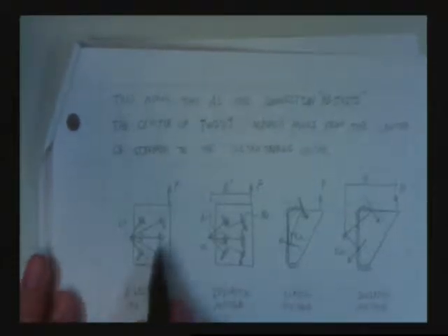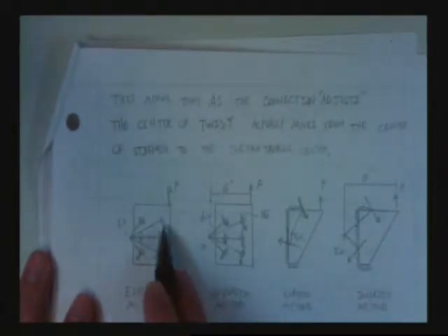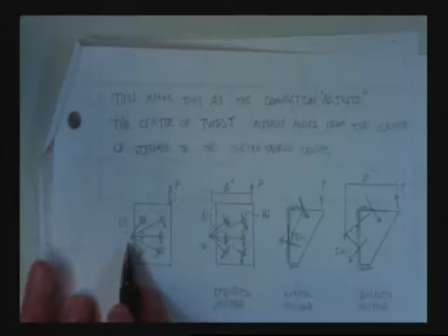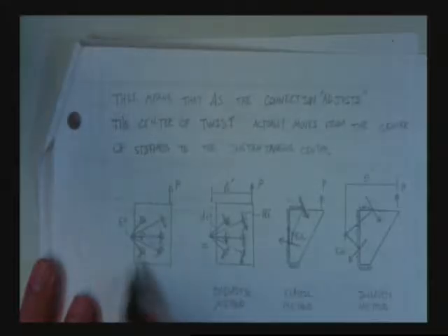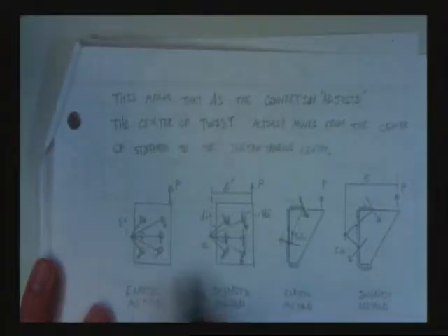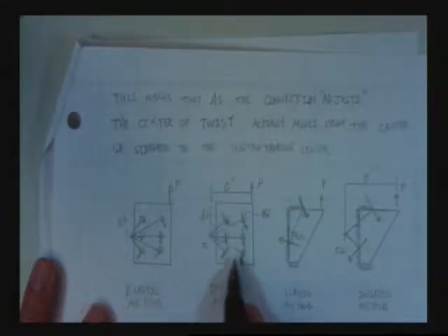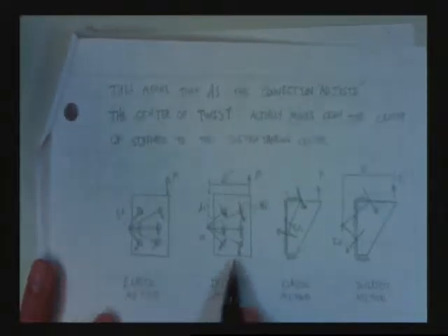Okay, so we just witnessed with our own eyes that when we started loading, we had members and bolts that were way away from our center, our elastic center of twist, that were heavily loaded, the bolts in the corner. And Jennifer, she wasn't feeling anything right here, nothing. They kept going, kept going, kept going. They adjusted until all of them were at their limit states. And it ended up looking something like this.